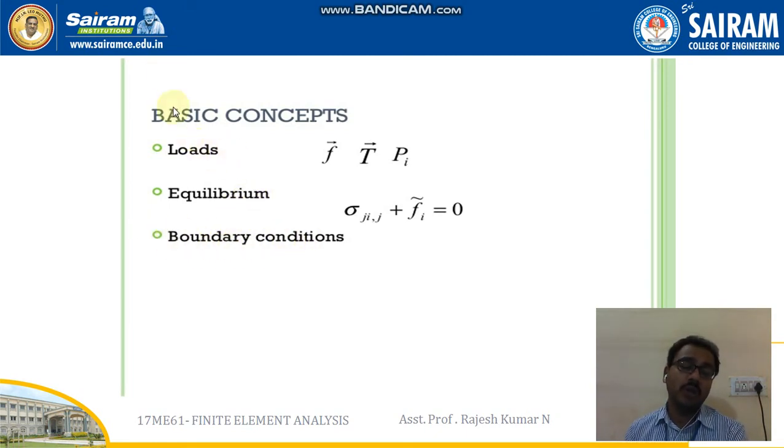So usually when we talk about the loads, depending upon the type of analysis we are doing, we can go with the force vector, a temperature vector and even a pressure vector. A combination of all three is also possible. Depending upon that, if it is individually asked, we will be going with only the force vector, and if the domain demands only temperature problems or analysis, then we will be going with only the temperature. And in case it is only pressure related, maybe a uniformly distributed load or uniformly varying load, then we will be fully going with the pressure vector.